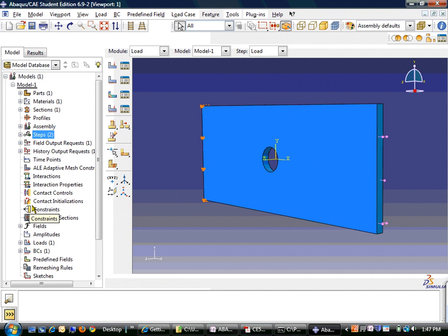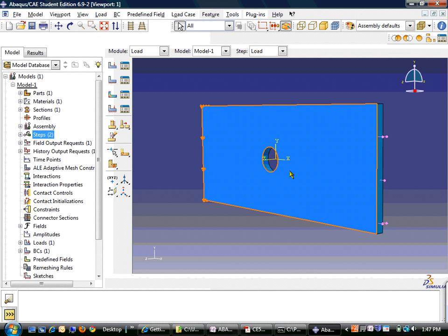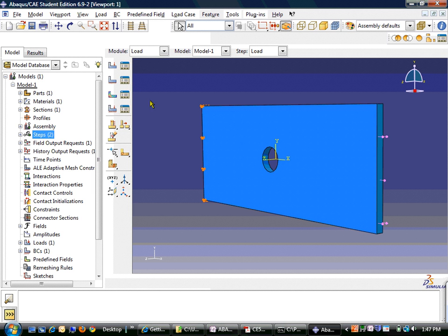Do you have a question? What's the difference between pressure and surface traction? Okay, pressure is always going to be normal to the surface. Traction, if you have the surface, in general, when you say sigma applied on n, sigma n is traction, and that can be pointing in any direction. So if you're shearing it off and applying a normal force, it could point in a general direction. So this is the tension pressure, quote unquote, that we have applied to this plate now.